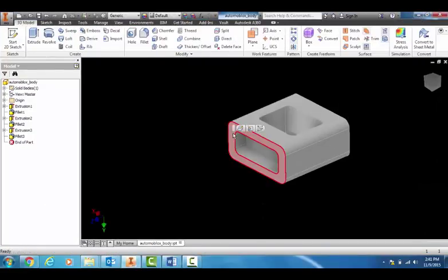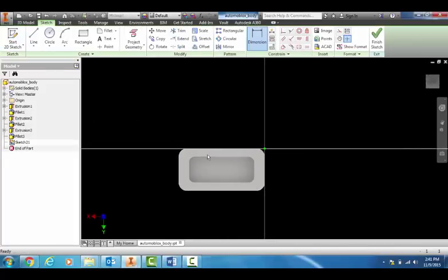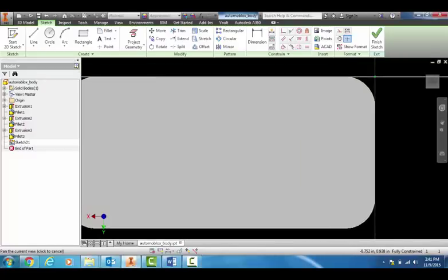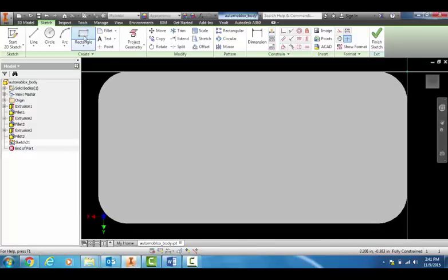Alright, so let's create these lines. Click on this face or plane, click Start 2D Sketch, okay, center it, zoom in, alright, let's come back to our rectangle tool, okay, find this line here, drag it out, okay, remember it's 0.06 by 0.06 inches, so 0.06, tab button, 0.06, enter, okay, if you remember it was 0.3 inches from this edge or surface, so come to our dimension button, okay, click that red line, click that red line, okay, and type in 0.3 inches away, okay.